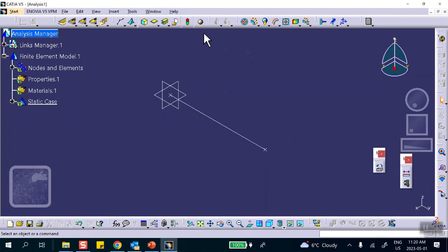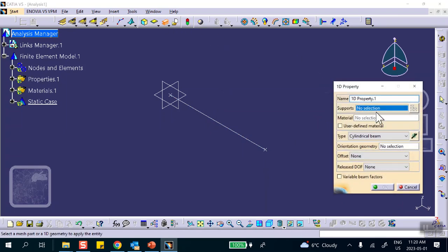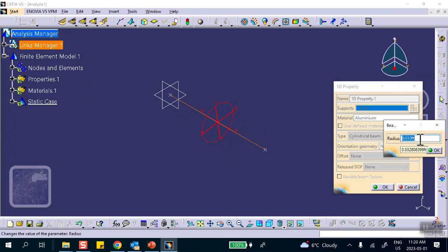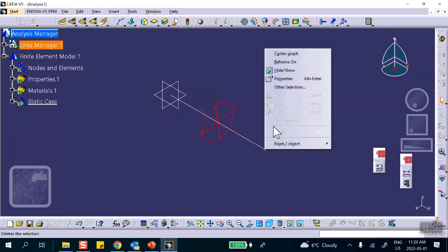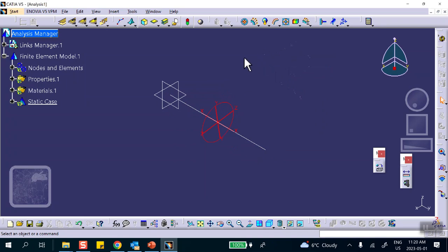And then we have to apply the cross-sectional properties. So you create the support. The actual size of this is irrelevant because these things are never used, but you have to do it. I can't remember what I did here. I put down some dummy numbers, 0.03 feet, doesn't matter. These things will never be used. Now we create a connection. Let me hide these points, because I don't want to inadvertently put clamps and restraints on them. I want to put them on the vertices at the end of the rod.